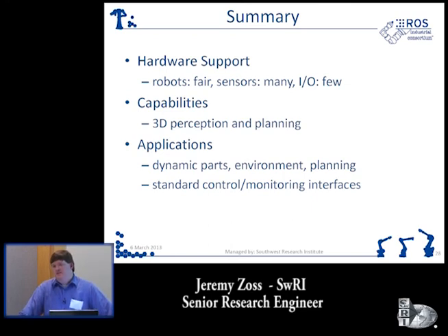So right now we have erred on the side of simplicity for the robot drivers. Essentially, the only commands that we send to the robot are lists of joint positions that the robot needs to follow, and primarily the feedback we ask for is position and velocity and some status information. So it's a minimal set of what you need to get the robot to function. And we've defined a standard socket message to get that data to and from the robot. At a minimum, if your robot lets you write raw sockets, which is a programming interface, and you can translate those sockets into motion commands for the robot and read the current position of the robot and translate that into socket messages to go out, that's the minimum of what you need.